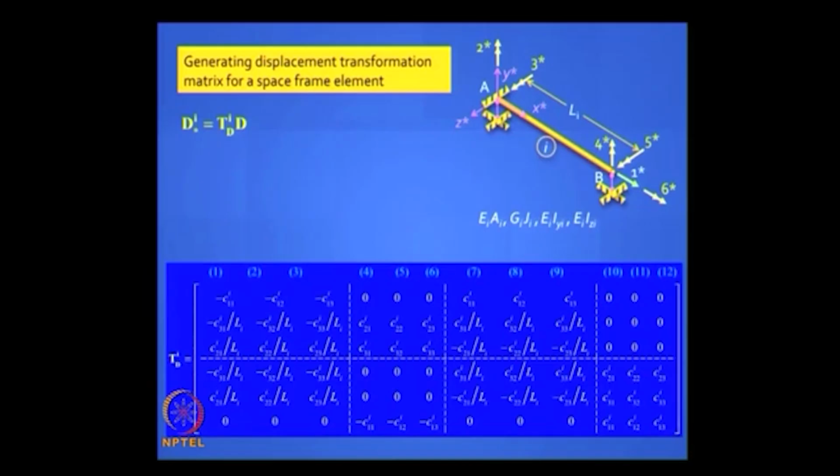The local coordinates. Okay, you need 6 local coordinates, right? Because the rank of that conventional stiffness matrix is 6. So you have to arrest 6 degrees of freedom. You have to cleverly choose those 6 degrees of freedom. Okay, then only that structure is stable, then only it can take any arbitrary load in any direction anywhere.